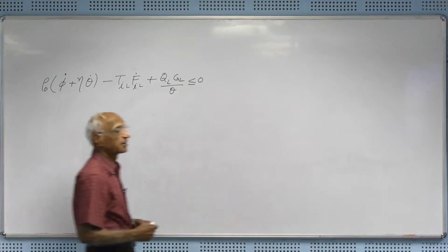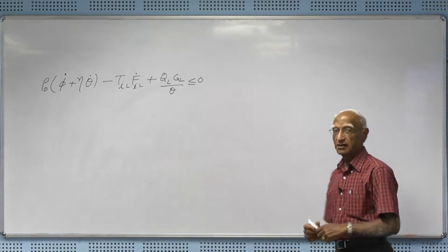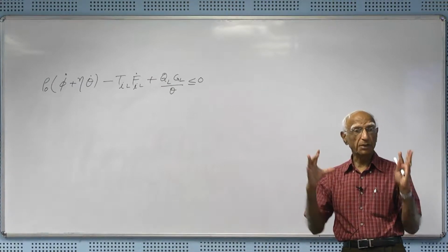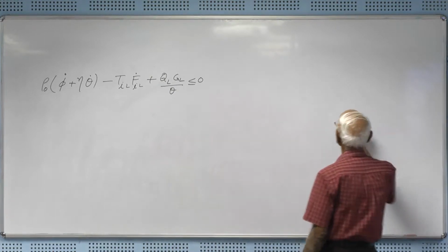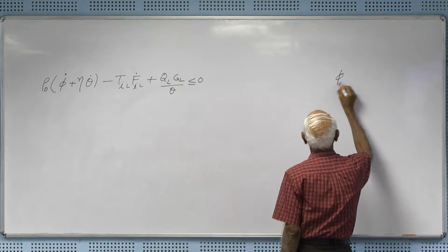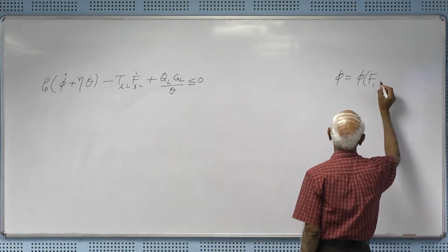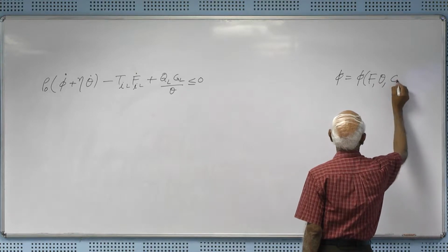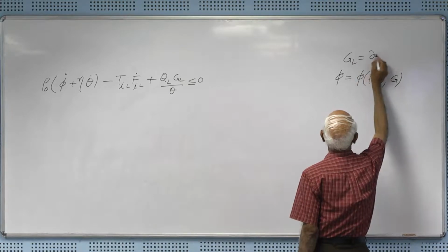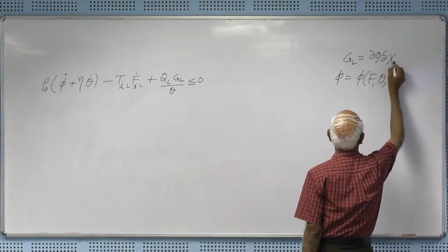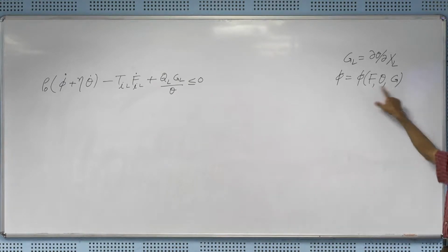And we said we will define thermoelastic materials. So we have now basically a bucket of materials. These materials have the property that all of these constitutive variables depend upon F, theta and G, where G_L is the temperature gradient. I did not put indices here, but anyway there are indices here, right?